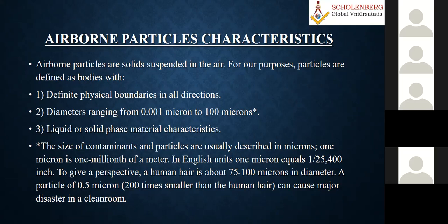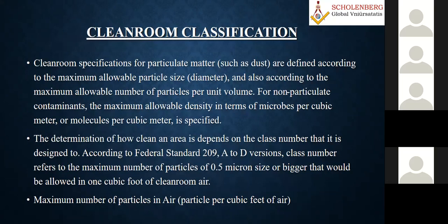Majority of the time, filter suppliers will talk about 95% efficiency or 99% efficiency. Efficiency alone doesn't matter unless you know the size of the particles it is going to control. That's why in our filter specification, in addition to filter efficiency, we very specifically specify the size of the dust particles. I have given this just to give you an idea.